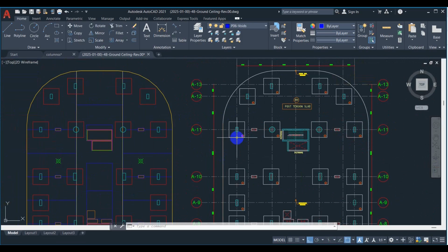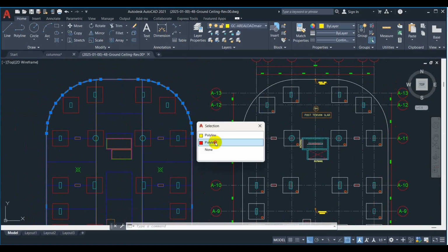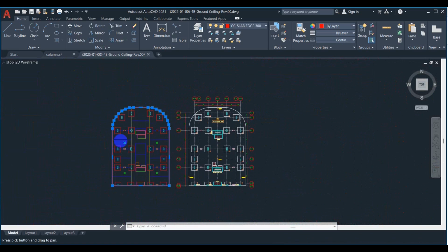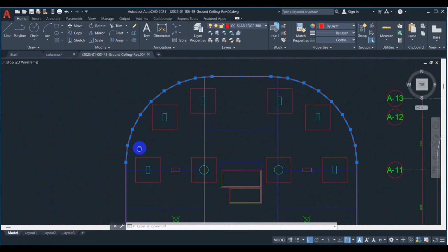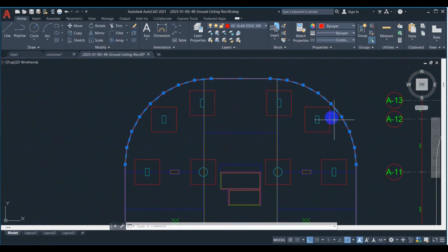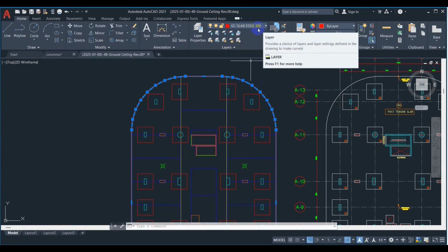When we are creating it, starting for example with the slab, it is a polyline as we said, without any extrusion and without curves. It's all polyline, with no too-closely spaced points. And the name of it is slab with anything else.